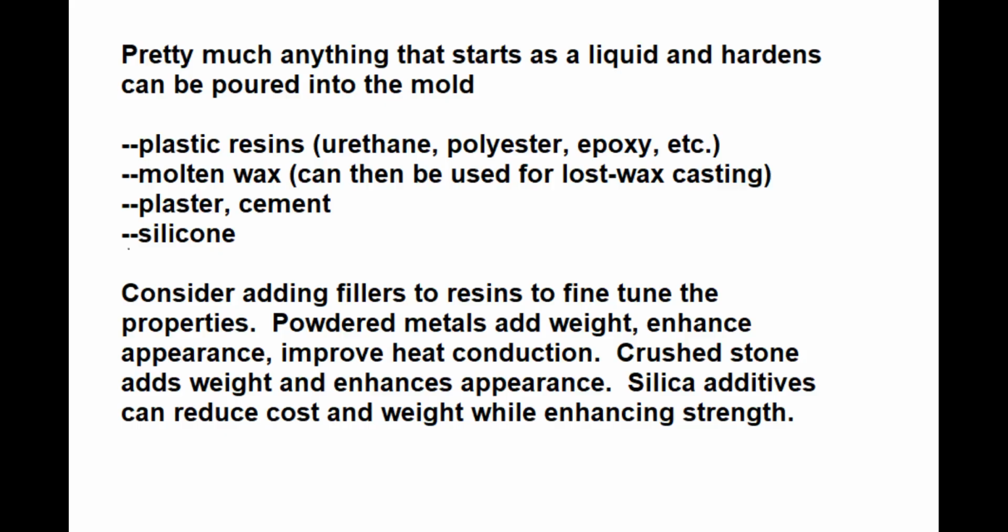Another nice thing about these types of molds, you can use them to cast all sorts of different plastic resins, wax, cements, plaster, really a wide variety of materials. You can make cast parts a lot more quickly than 3D printed parts. Some resins will cure in only 10 to 15 minutes. The parts are going to tend to be more durable than 3D printed parts. Also, the cost of the resin is generally much less than the cost of 3D printing supplies, so the per part cost tends to be less.